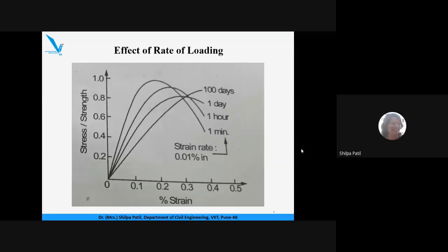Do you remember those values? Ma'am, there was some rate fixed depending on that compressor machine. Yes, correct. But right now you must not be remembering that value. Yes, ma'am. So normally the constant rate of stress increment of 14 Newton per mm square per minute is the expected rate. And the stress strain curve plotted for that particular rate is normally considered for design criteria.